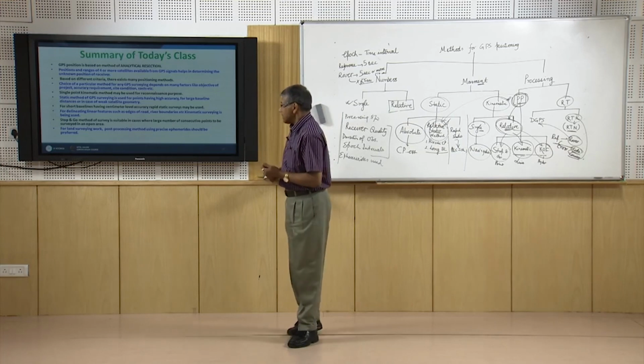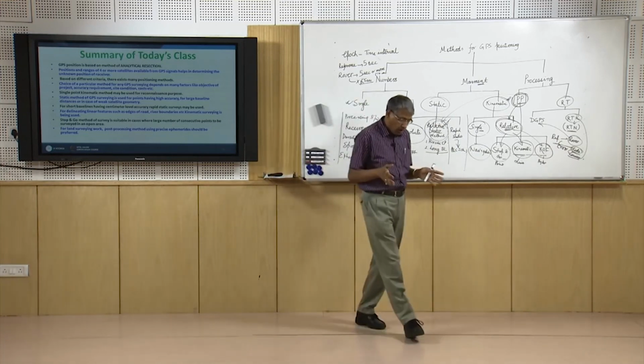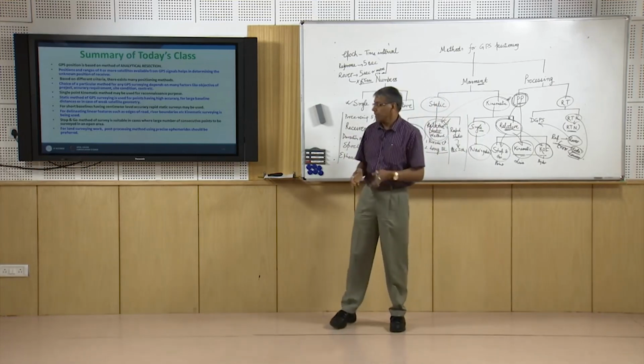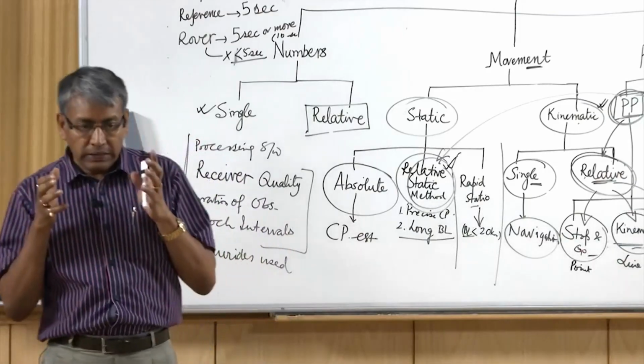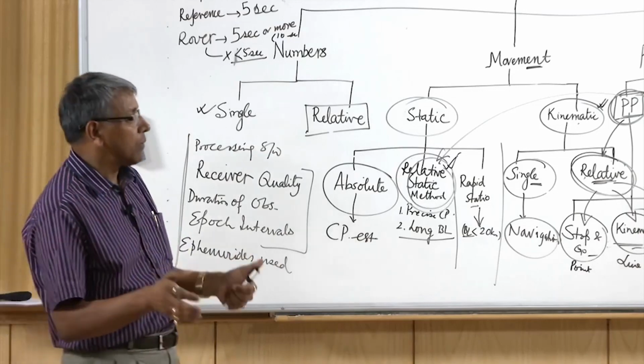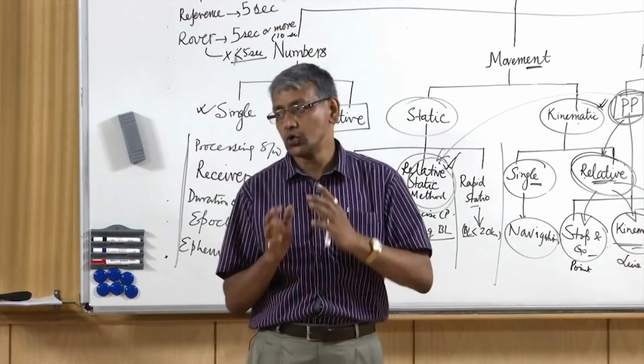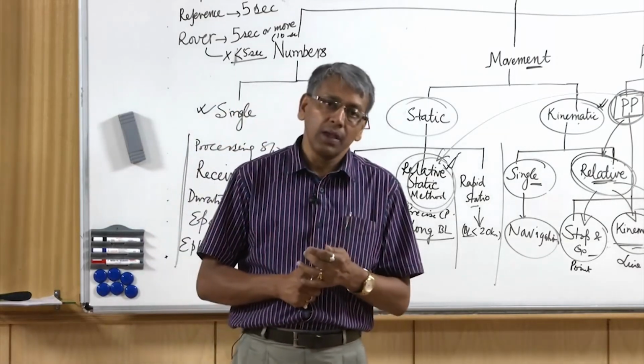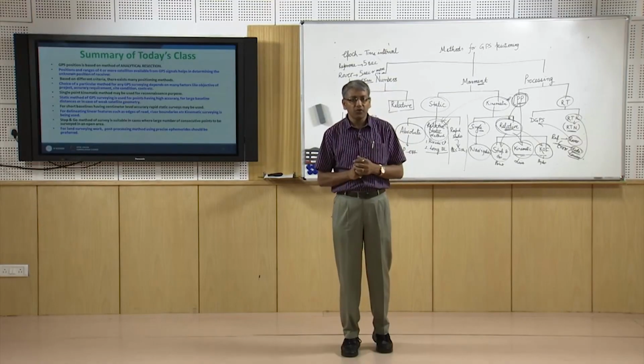And for land surveying work, it is always advisable to go for the post processing mode of GPS surveying, and if we want to end up with very accurate results, we should go for the post processing GPS surveying method along with precise ephemerides. Thank you very much.